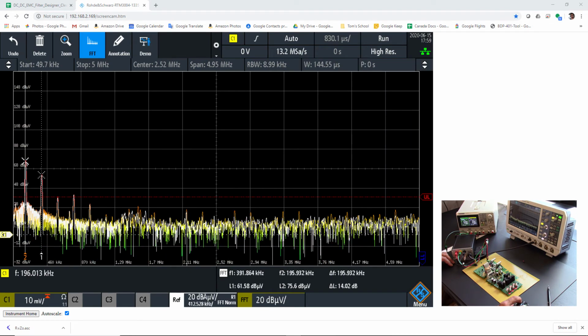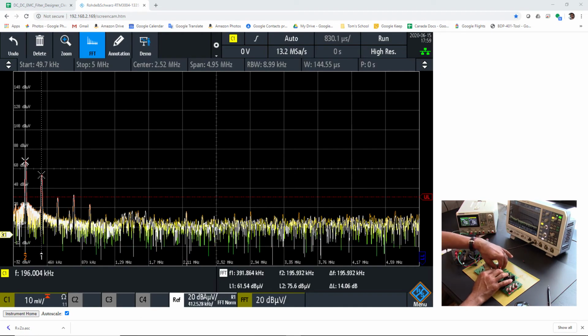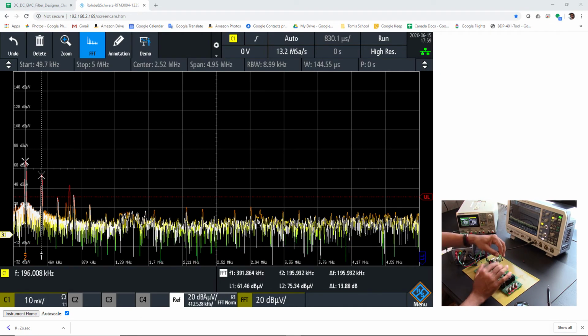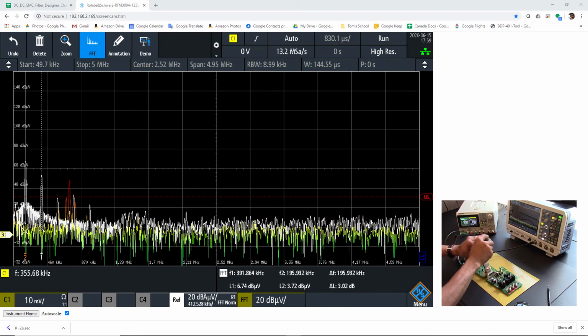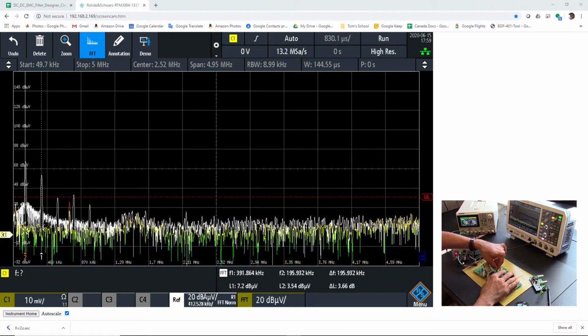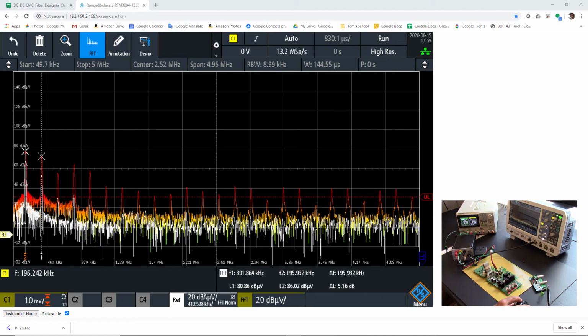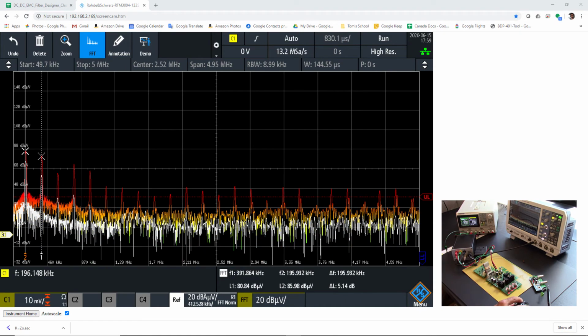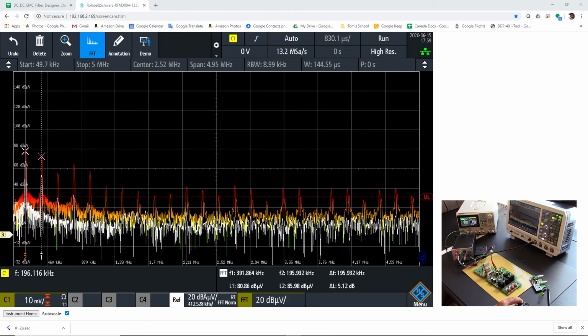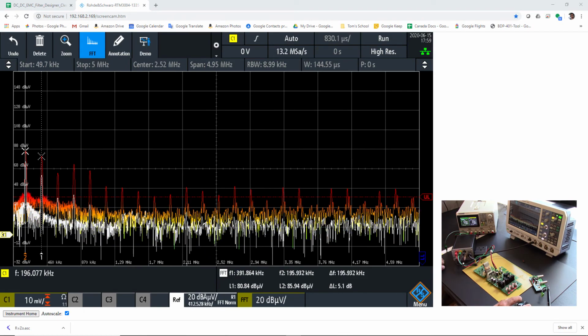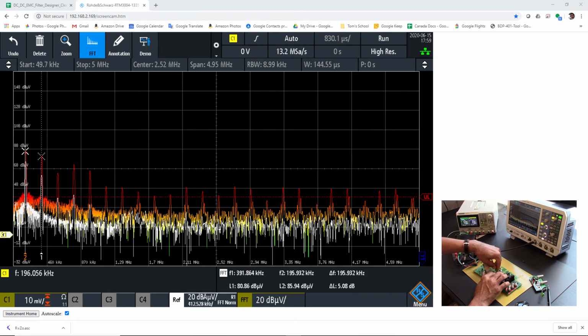the harmonics after filtering. So I now can remove this, and I can add now. There we go. So what you see here is the harmonics before filtering, the red and orange line, and the white line is after filtering. So you can see how much this one filter has attenuated our noise.